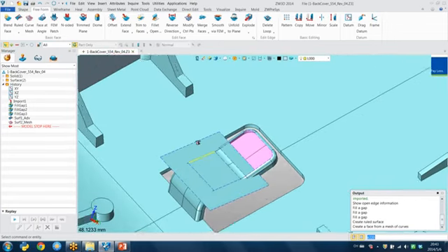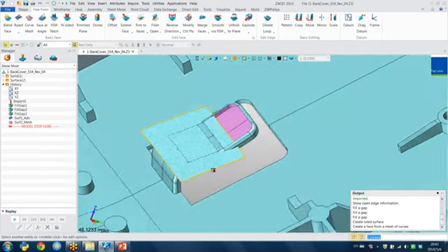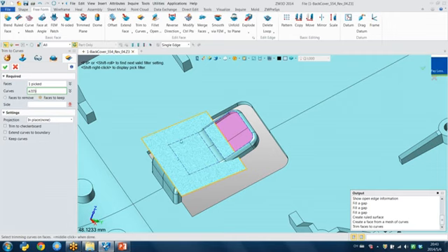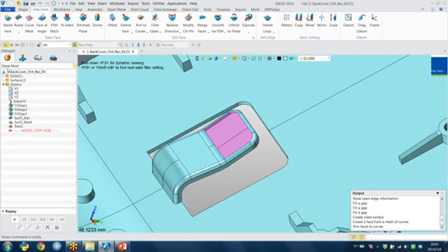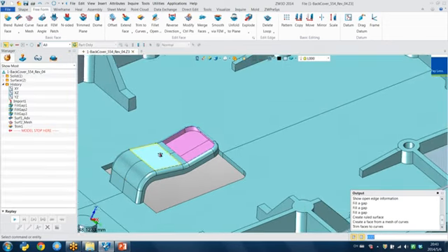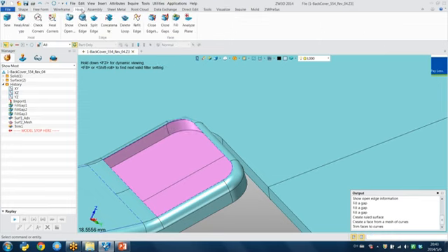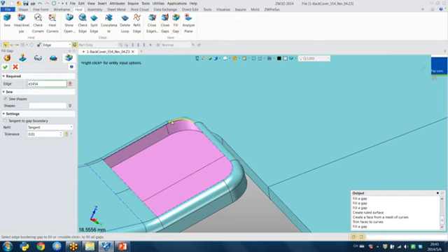So in this area, you can find this surface, or you can use the trim to curve. So you can select the curves. Press OK. Select the face to keep. Okay, I want to keep the inner one. So press OK. So for this area, you can also use the powerful function fill gap.